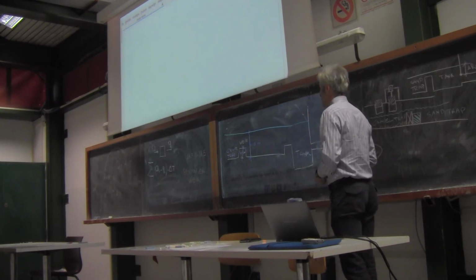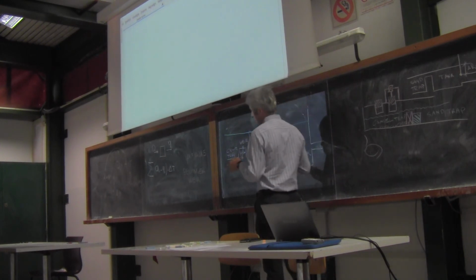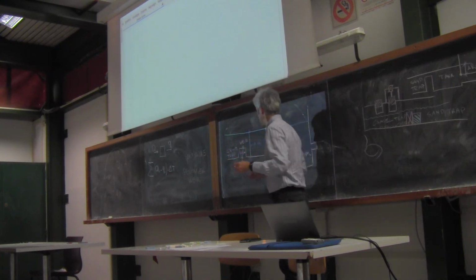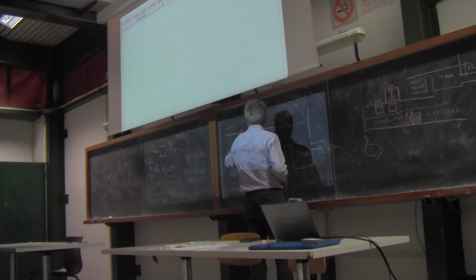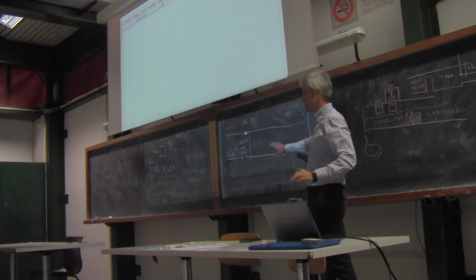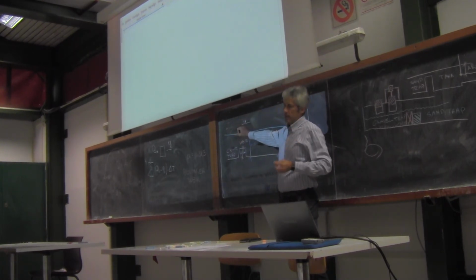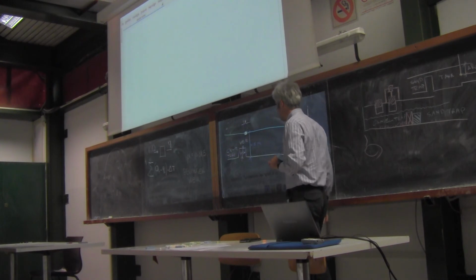Okay, good. Now, let's suppose that at the entrance of the sand trap we have a particle of sediment that is located here. And the diameter is d. This diameter is prescribed by the producer of the machinery downstream. We already talked about it.